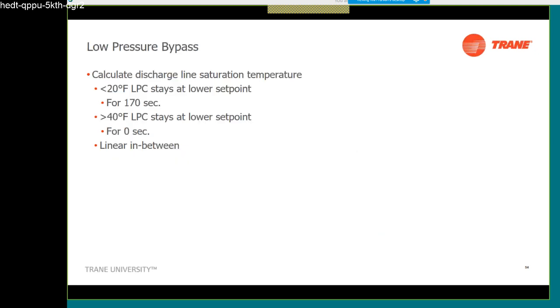Low pressure. Oh, hold on one second. So back to the balanced wear thing, that's going to be under settings, and it's under feature settings to enable or disable balanced wear. I had to reconfigure my panel. Fine. I have to reconfigure it again now to go check for that hot gas bypass set. We can't have balanced wear and hot gas bypass. Right.